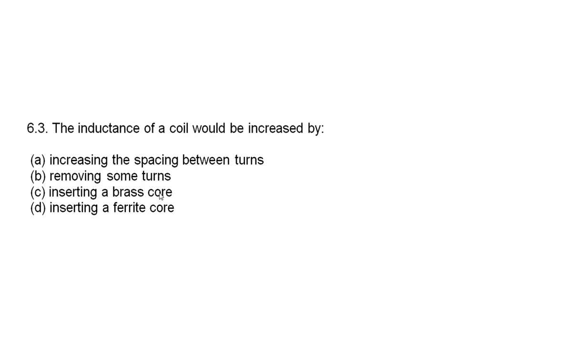Increasing a brass core. Well, brass is not a magnetic material. It has a permeability of less than 1. It does not concentrate magnetic lines of force. So that C would not be the correct answer.